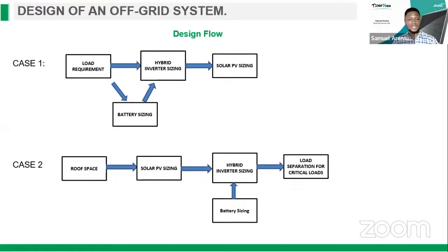One thing I actually tell people is that you don't size your inverter based on the load requirement alone, because in the case of a hybrid inverter, remember that it also has an inbuilt charge controller. That means the inverter also charges the battery, so it sees both the load and the battery itself as a load. You need to consider the charging of the battery as well when you are sizing your inverter.